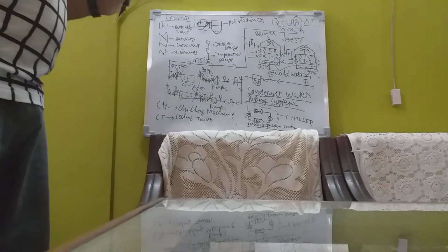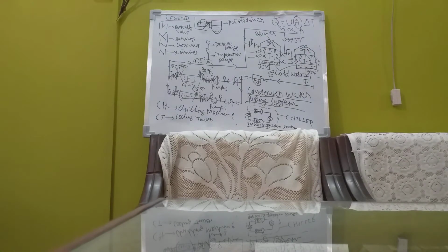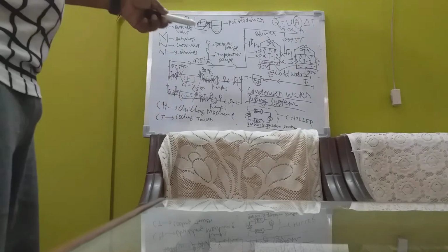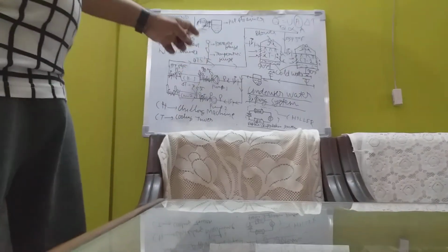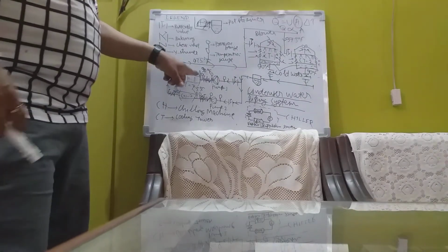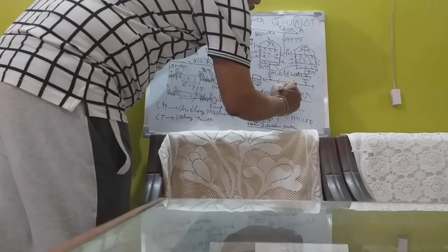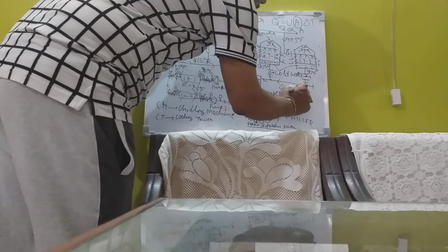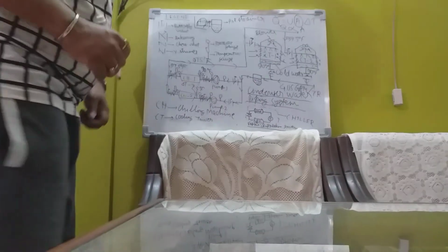You have to understand that connotation clearly. This is how the whole system works here. This is the condenser water system. Remember, here the delta T is 7.5 degree Fahrenheit. That gives you a GPM of 4 US gallons per minute per ton in case of condenser.